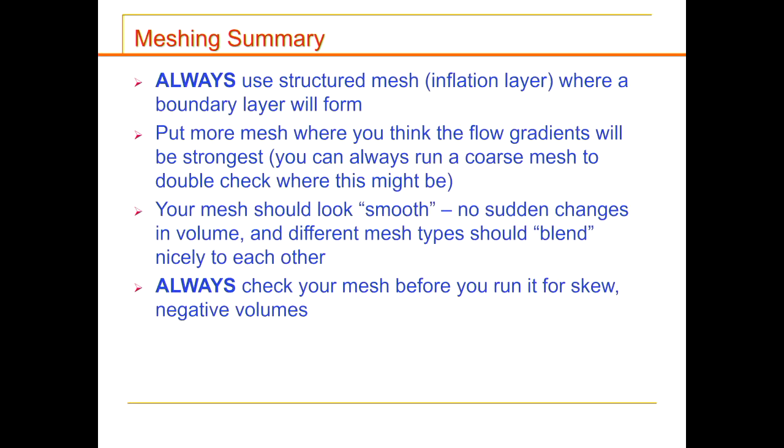Most important, especially when you start looking at complex geometries, always check your mesh for negative volumes. Because if you don't check and you get a solution, it may be very far off. Even though it runs and looks okay, it could be wrong.